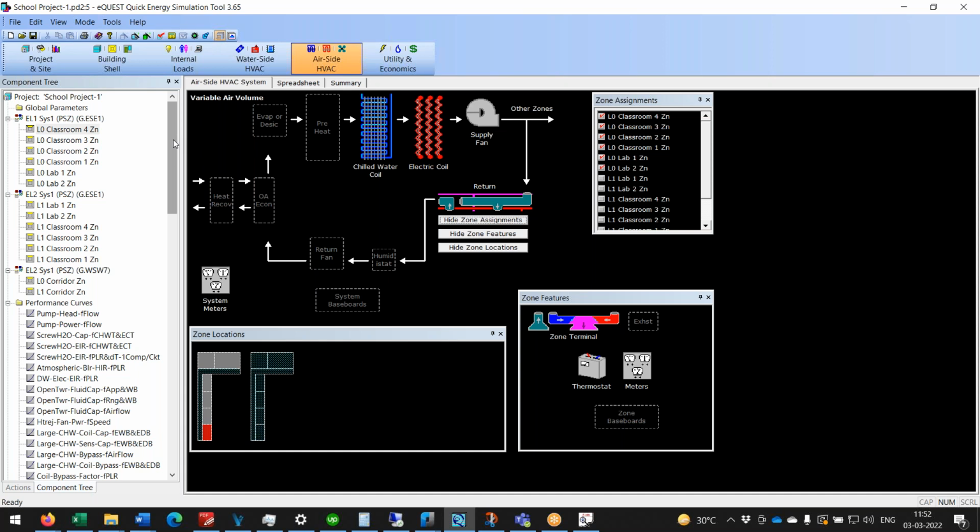And one more thing is the treated fresh air unit. I think that also you need to give specifically. Sometimes even in chilled water units, they give TFA units, treated air or dedicated outdoor air units. And in fact in VRF it is very much required because you have to give the pressure. So what would you do in those cases? What is happening is the pressure is being drawn from a separate unit, which is called a TFA unit.